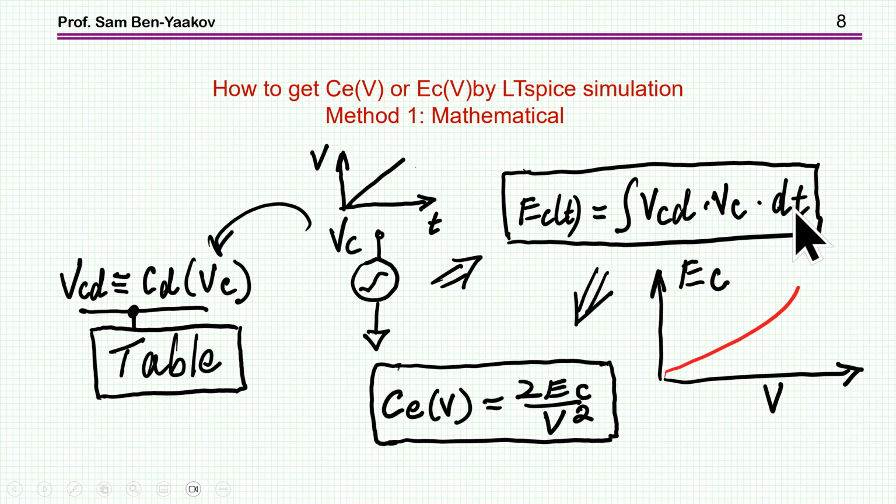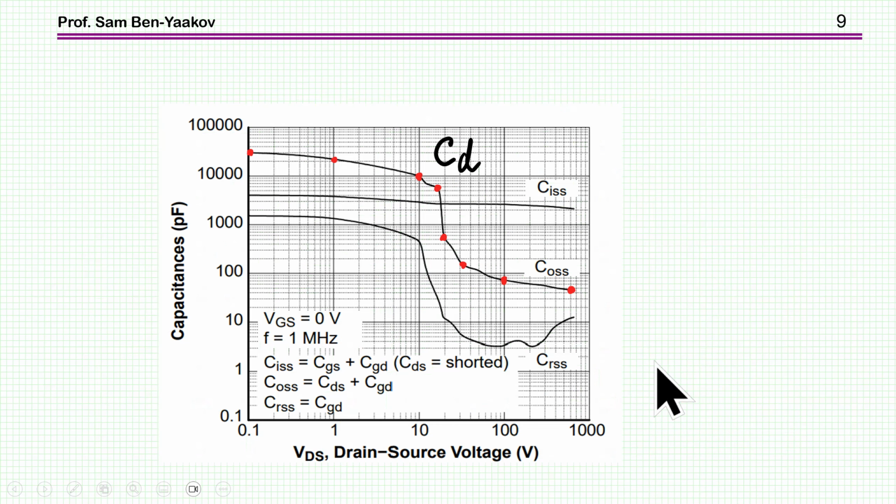You can do that. And then once you get this information as a function of time, which is also a function of the voltage, because this is now linear, you can use this energy to calculate on the run, as a function of the voltage, the energy-related capacitance. And then, of course, you can plot this information as a function of voltage, which is again linearly related to time.